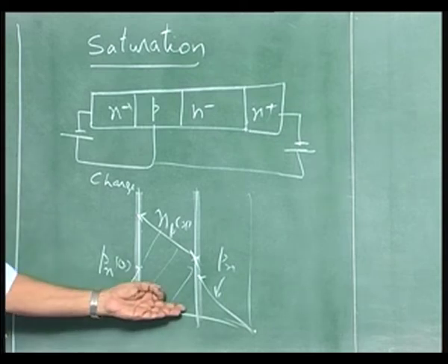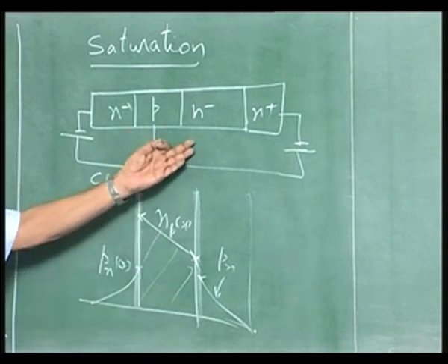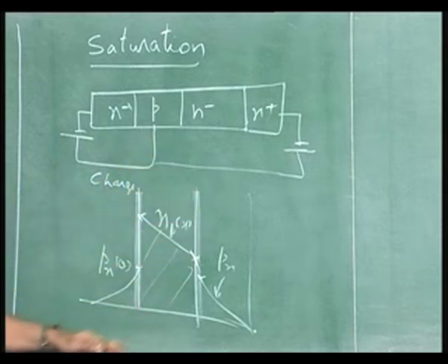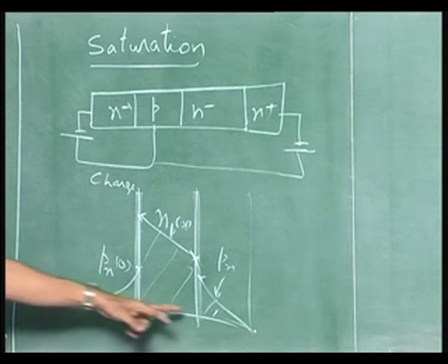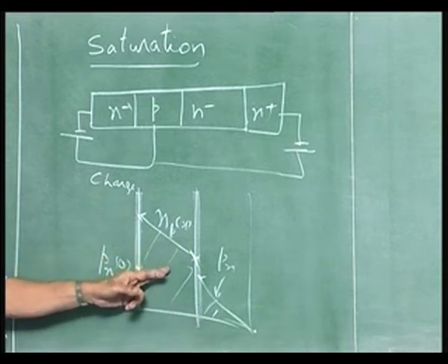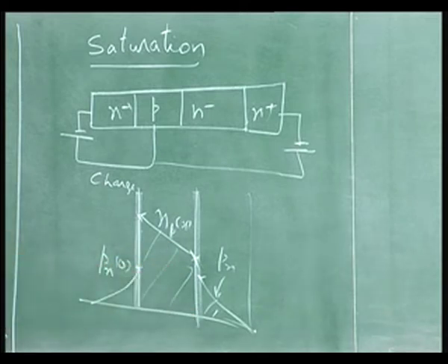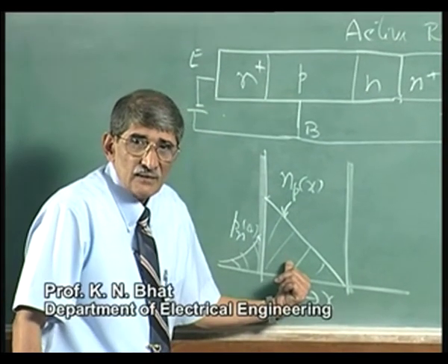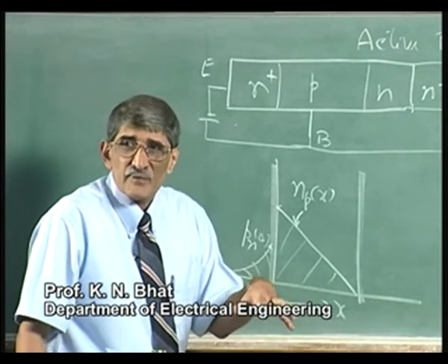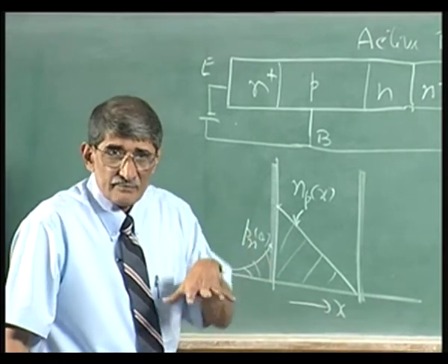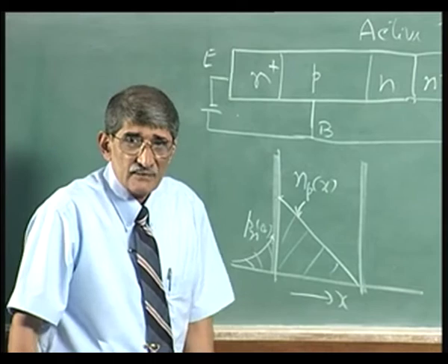Injected holes, pn junction forward biased, holes are injected there. That will be another thing. Now, you can see the problem is compounded when it goes into saturation, but if you use emitter coupled logic, you can cut down at least that stored charge here. You can cut down this charge, but still you have this stored charge. If you take the MOS transistor, it is much smaller, in the form of majority carrier.